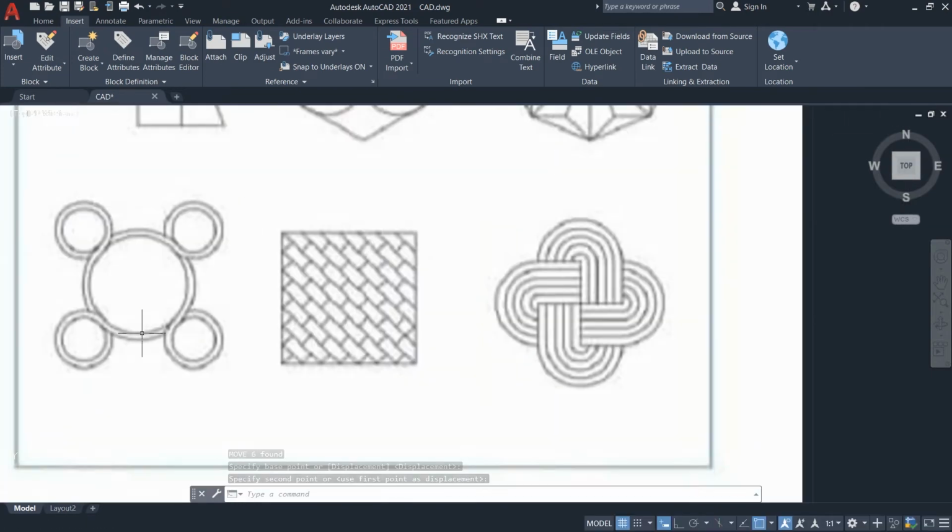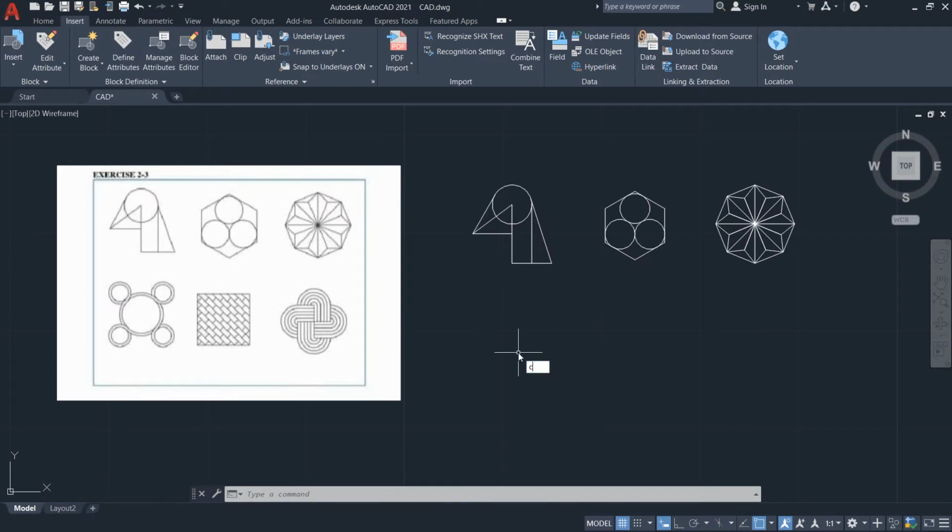Let's start to this part 1. First, type C to create the inner circle measuring 3.5 as its radius. Make a horizontal line intersecting the center of the circle. Type L to have those lines measuring 5.25 from the center with an angle of 45 degrees. Then, extend it as 5.25 again, diagonally. To have the next diagonal line, type line measuring 5.25 again with an angle of 135 degrees.